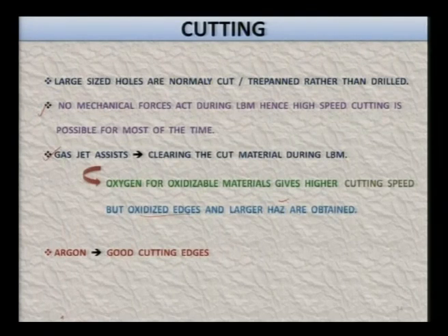Argon is a good assisting gas, with the help of which you do not get oxidized edges, and the cutting edges are also sharp, better compared to what you are going to get in the case of oxygen.